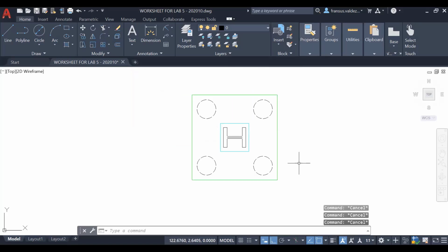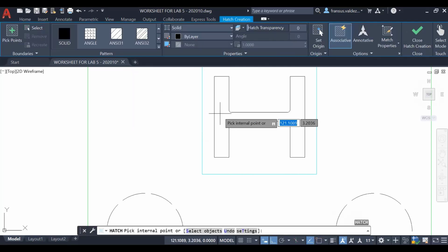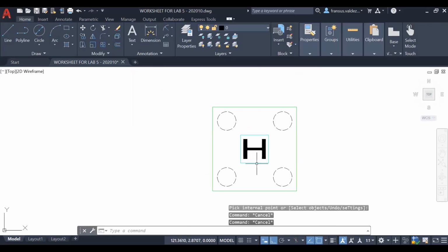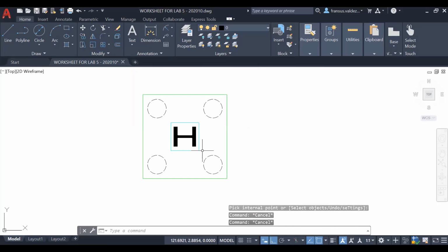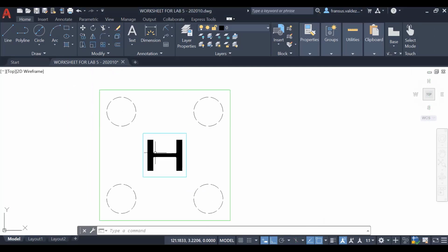And then this one, I remove this center line here and then I hatch it. Hatch, so this one is black, white background, so this will be black. Hatch, command H, and then click this one here. That's it, so we have it already. Now let's make a layer for this one. They are not mentioned in the layerings. No layers provided for the files, so let us layer now.